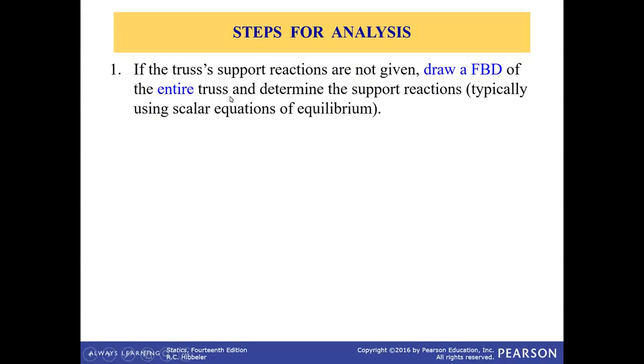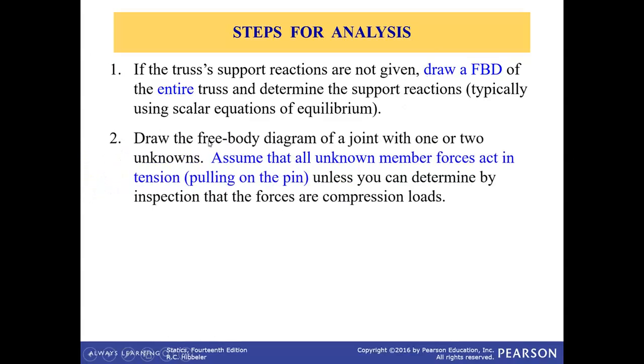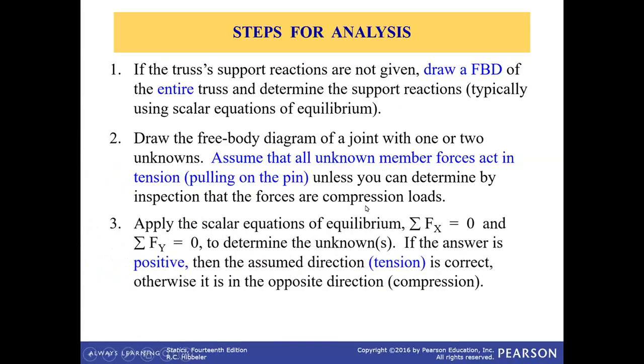So the steps for truss force analysis: if the truss's support reactions are not given, then draw a free body diagram of the entire truss and determine the support reactions. This is what we learn in chapter 5. Draw the free body diagram of a joint with one or two unknowns. Assume that all the unknown members act in tension unless you can determine by inspection that the forces are compression loads.